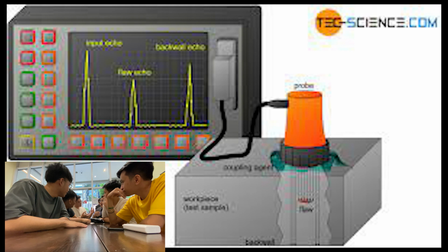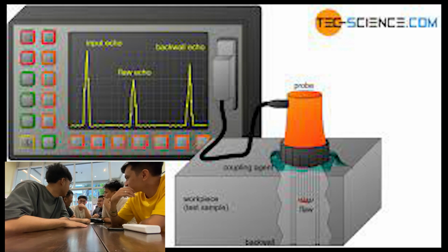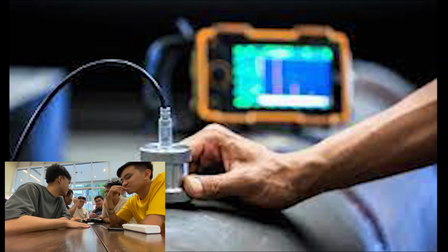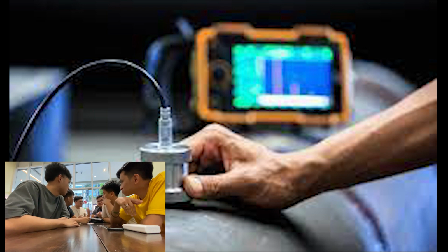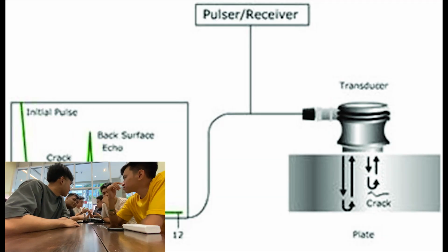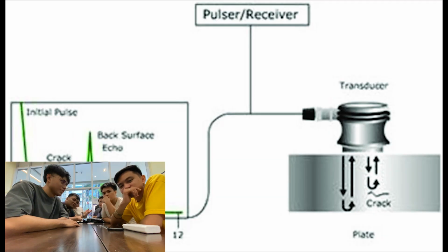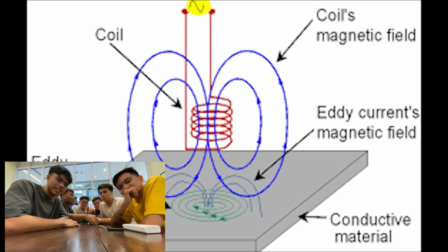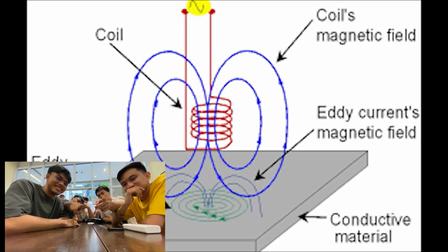Second, sonic testing. Ultrasonic sound energy is transmitted through a coupling onto the metal. These ultrasonic pulses bounce off the metal and are converted into electrical signals. These signals will show the location of pits and other imperfections in the metal. And lastly, electromagnetic testing. This testing method is used to locate irregularities in the surface of conductive metals like steel and iron.